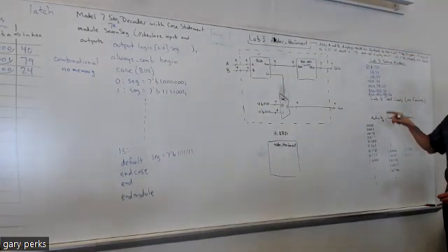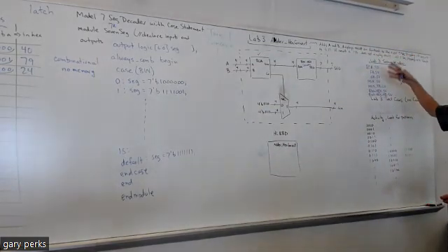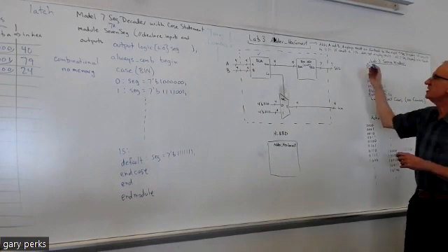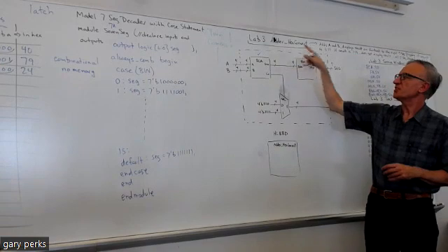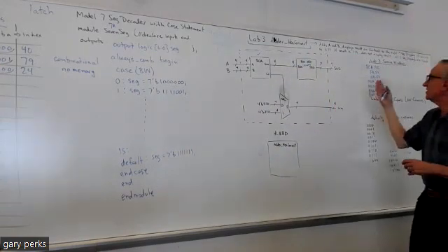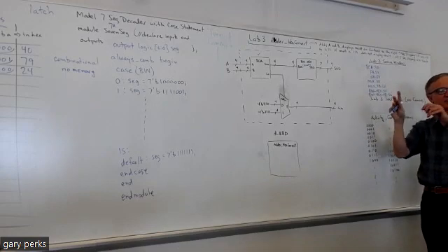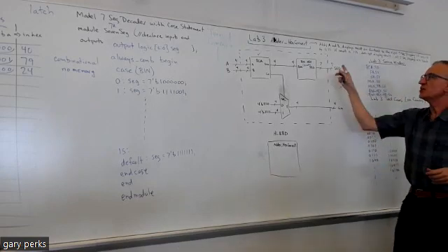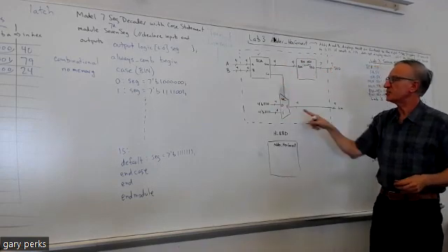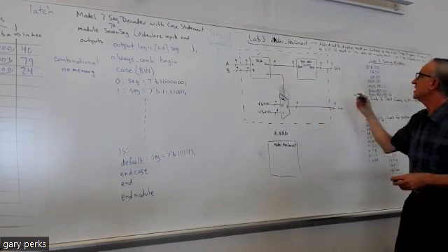Okay, so you're going to need these design sources, these test benches. You'll also need a design source that's going to connect these all together. Just like the RCA connected the full adders and the half adder together to make the adding circuit, you're going to need a structural model, a top module that makes the connections between these modules.